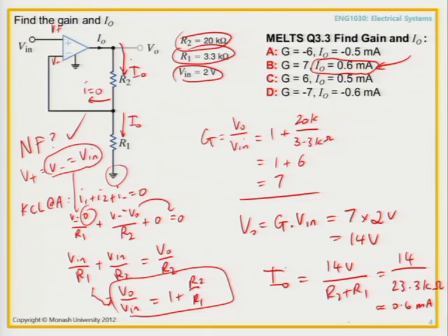Yep. In the first case we found that the direction of I0 is up, then in the second case down. Does it really match with this sign? Okay, this is a good question because it can get confusing. Why do I say I0 is coming out this way? It's because in the question you're asked, you've been given a definition of the direction you need to find I0 for. So I need to make sure that when I do my calculation of I0 in this case, I take V0 minus 0 divided by the total resistance.